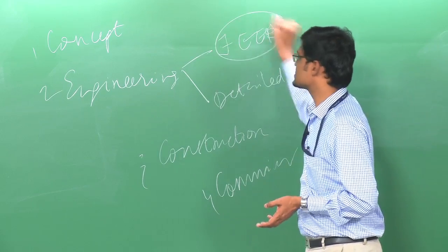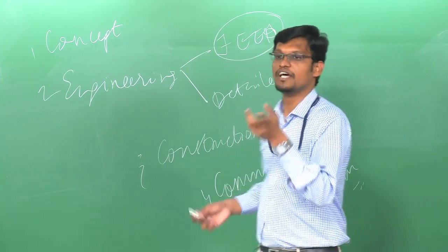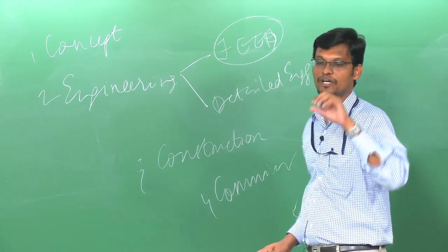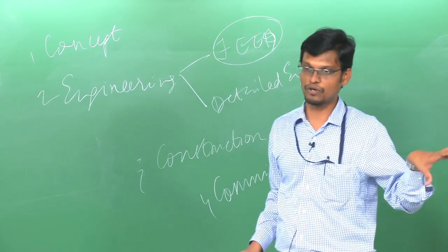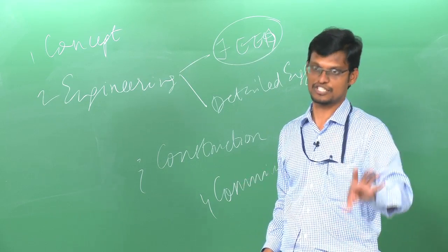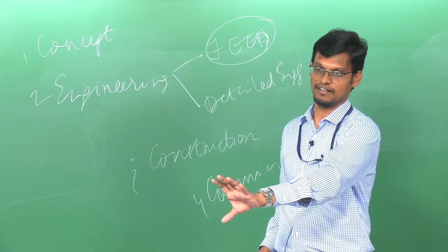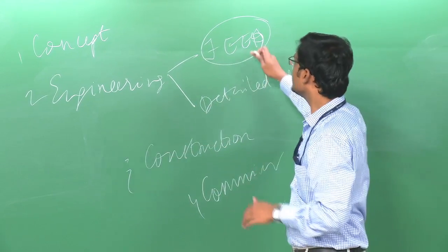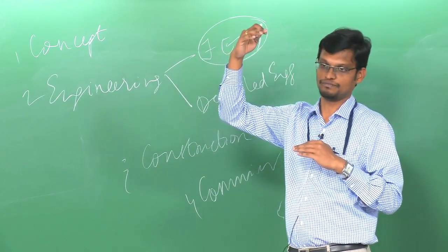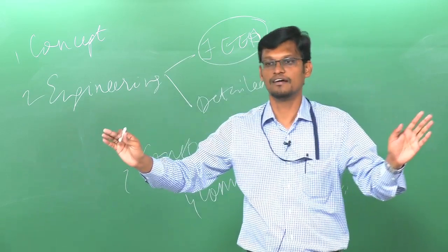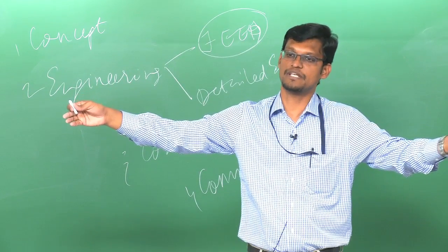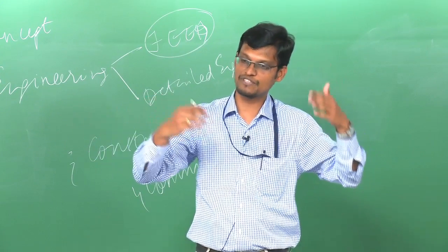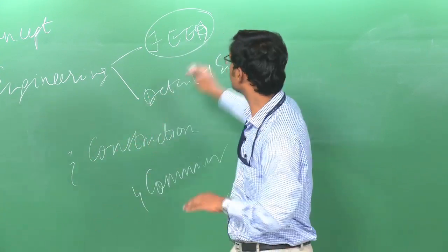Now, somebody asked me what is FEED, right? FEED is nothing but front end engineering. See, it is detailed engineering where you get into the finer aspects of it. Like for example, you want to lay a pipeline, you will say it's 12-inch, carbon steel, supported at so many points, above ground, underground type of thing. FEED is slightly one level above. You only know that you want a pipeline for 10 kilometers from this place to this place. You do not even know what the diameter is, you will not even know how much of the pipeline is going to be above ground, below ground, whatever. So, that is at this level.